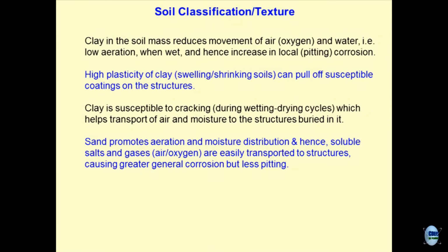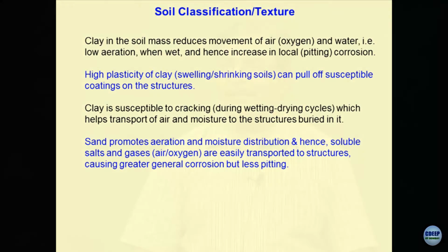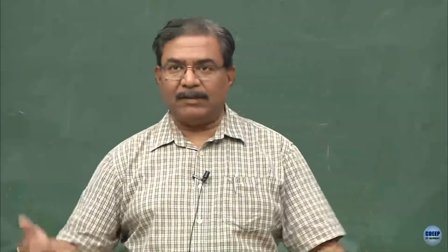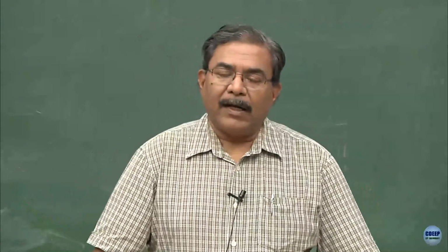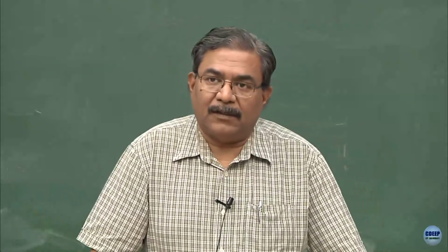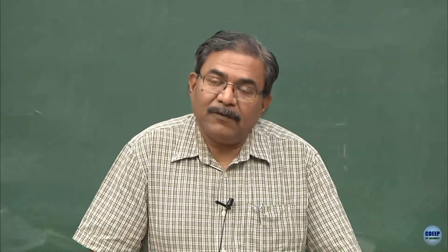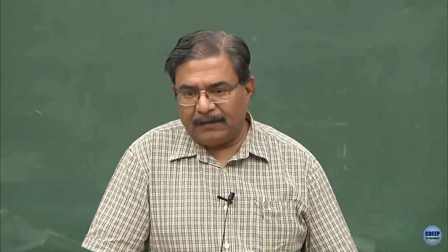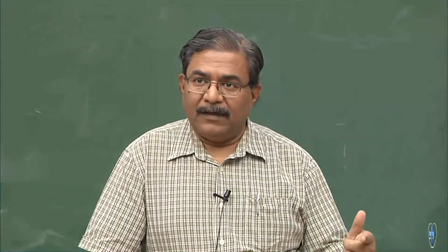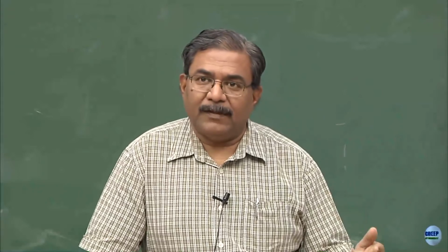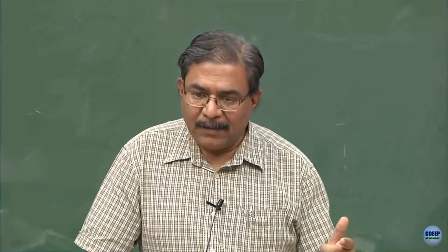So, on the contrary, when you use sands, what will be the problem with the sands? Densities. If I use sand as a backfill material, which is the most ideal situation, I can't achieve the better densities, is it not? But at the same time, you will study sometime later that sands have high permeability, high thermal diffusivity, and thermal resistivities are going to be less, and hence they are the better material for using as backfill.